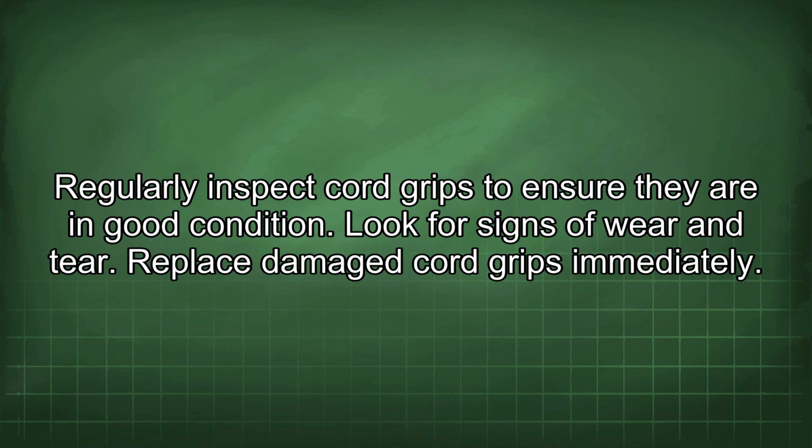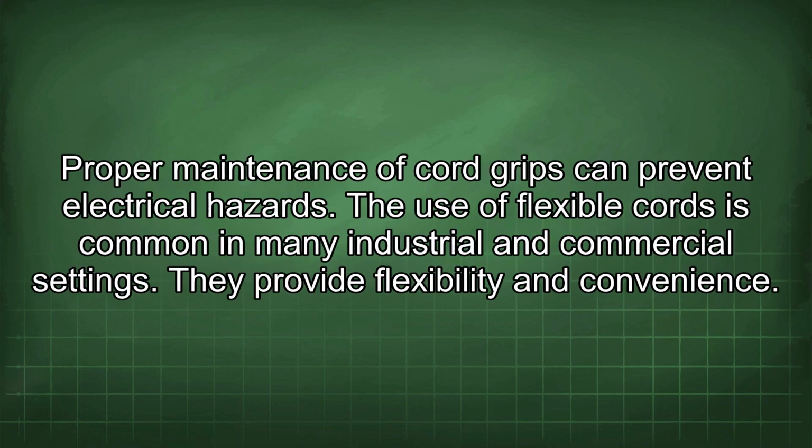Look for signs of wear and tear. Replace damaged cord grips immediately. Proper maintenance of cord grips can prevent electrical hazards. The use of flexible cords is common in many industrial and commercial settings. They provide flexibility and convenience.